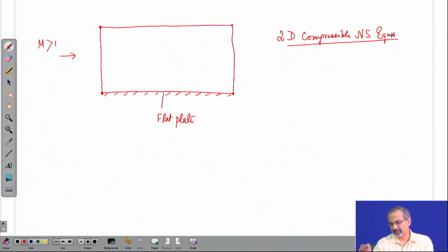in order to generate the viscous solution that develops when that supersonic flow moves past this flat plate. Now, because it is viscous, as you can understand, obviously there will be a boundary layer formation on the flat plate, irrespective of whatever Mach number it is. And the boundary layer thickness delta also has an accompanying displacement thickness, right.